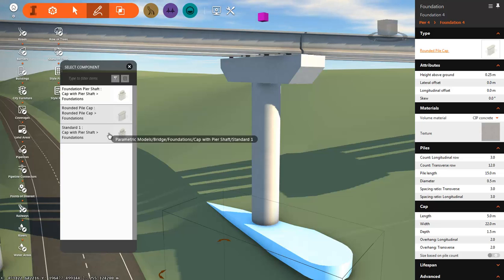They're all piled foundations. I'm not looking for piles at this stage on this particular one. And I've got a very specific size and shape which I want to achieve here. It doesn't look as though I'm going to be able to achieve it with what's built in. So what we can do is use Inventor to create our own footing and bring it into InfraWorks such that it behaves exactly as those other 3 would do. Okay, so let's have a look at that.